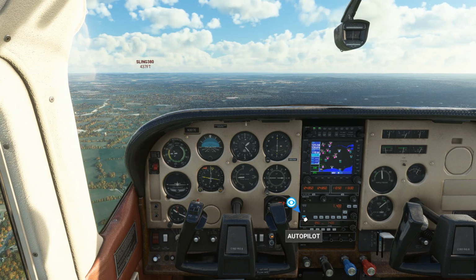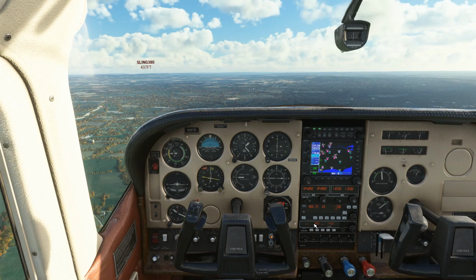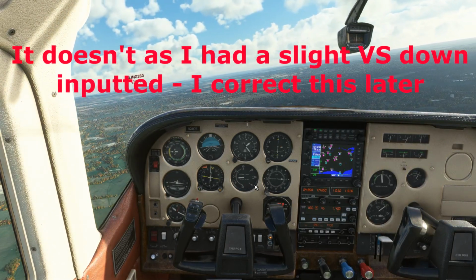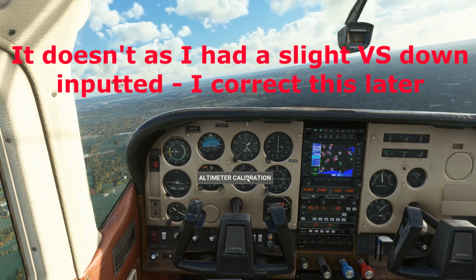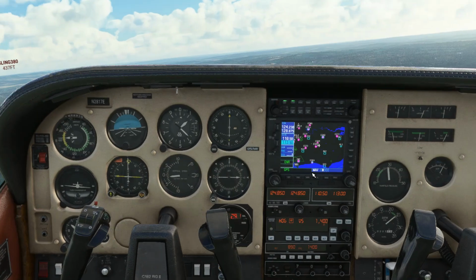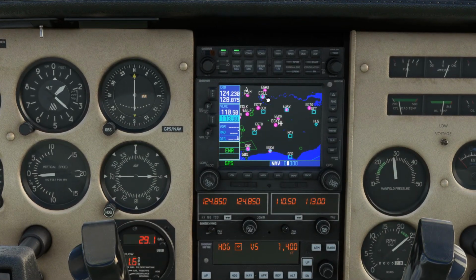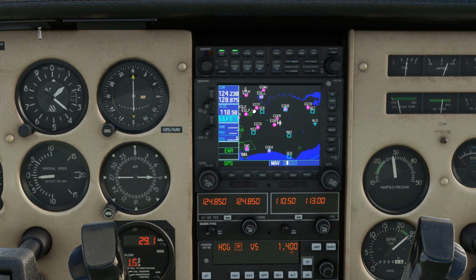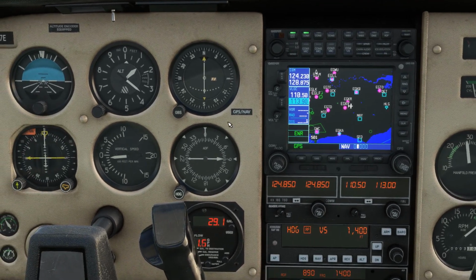I'm going to put it back into autopilot mode and heading mode. And it'll keep us at 1,400 feet and a heading of 90 degrees. Now we're doing that, I'm going to come down here to see where ACTUAL is. It's up here. Soon I'm going to want to turn north and I'll manipulate my heading mode again.